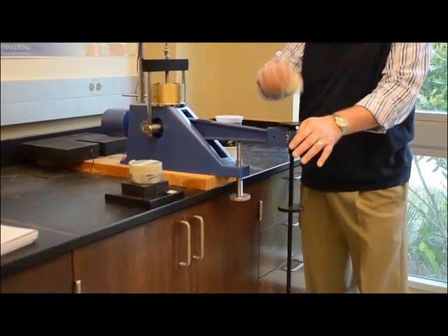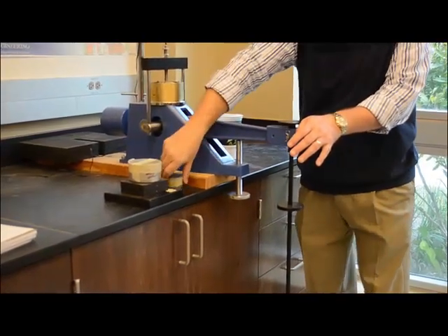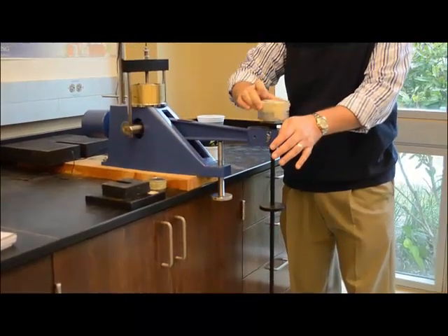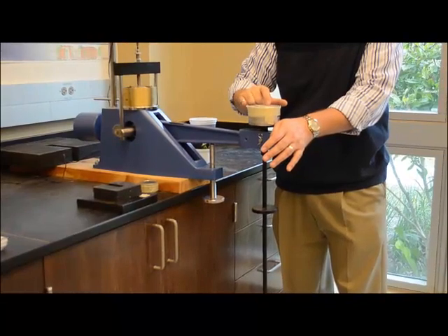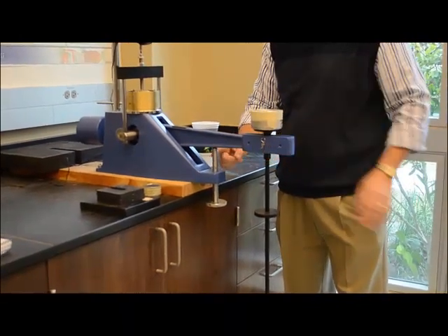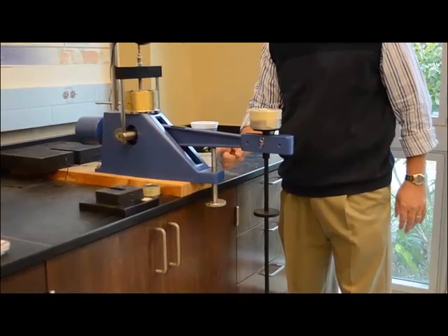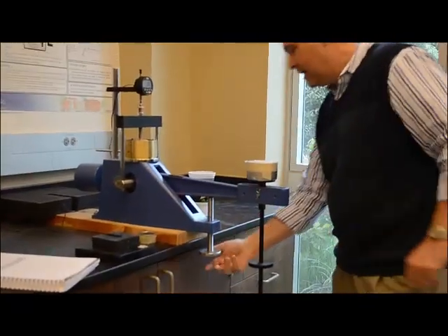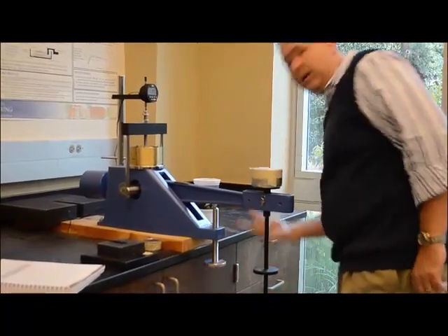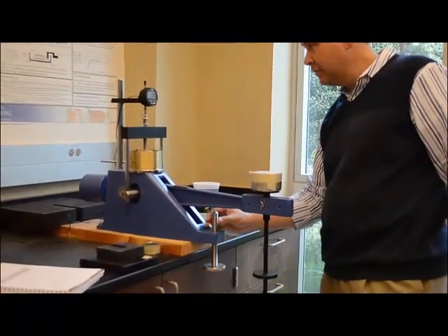And now what we want to do is we want to hold down the load onto the loading jack to where whatever load we place onto that is not felt by the sample quite yet. And so I'm holding it down with my left hand and placing the load that I want to be. This is our first increment of load. And then I look at the time, and then I release the loading jack, so that load that's on the hanger is put onto the sample now.